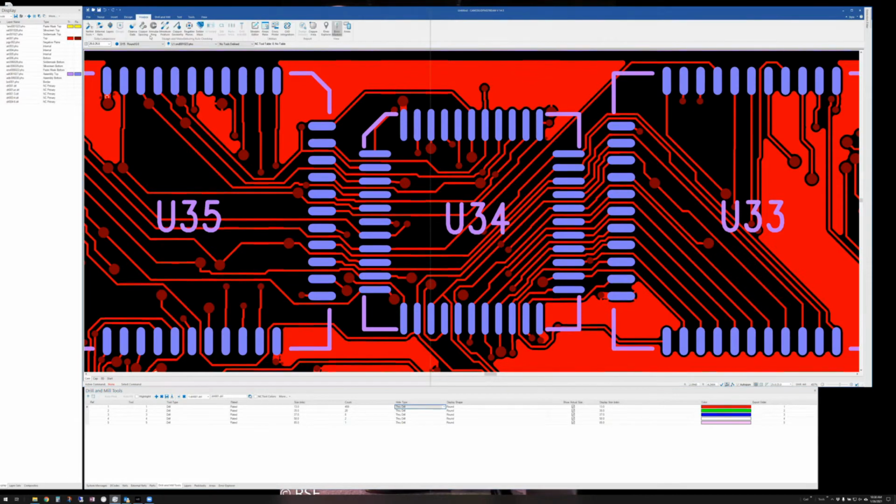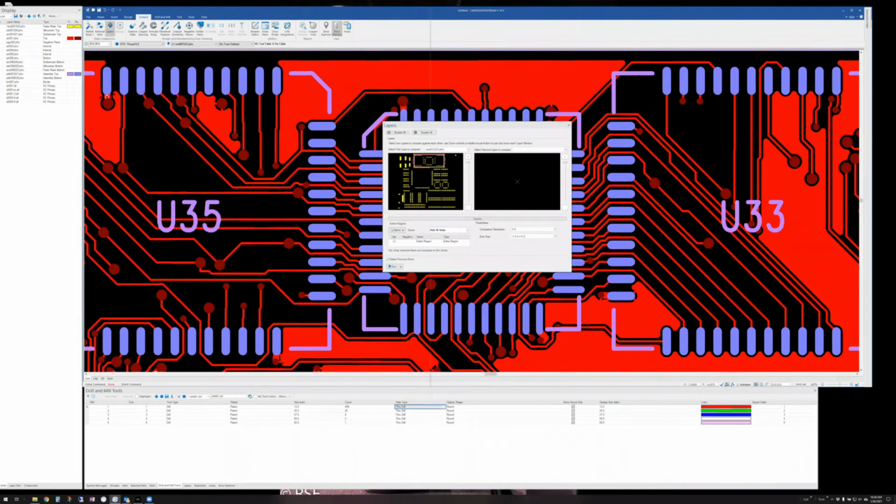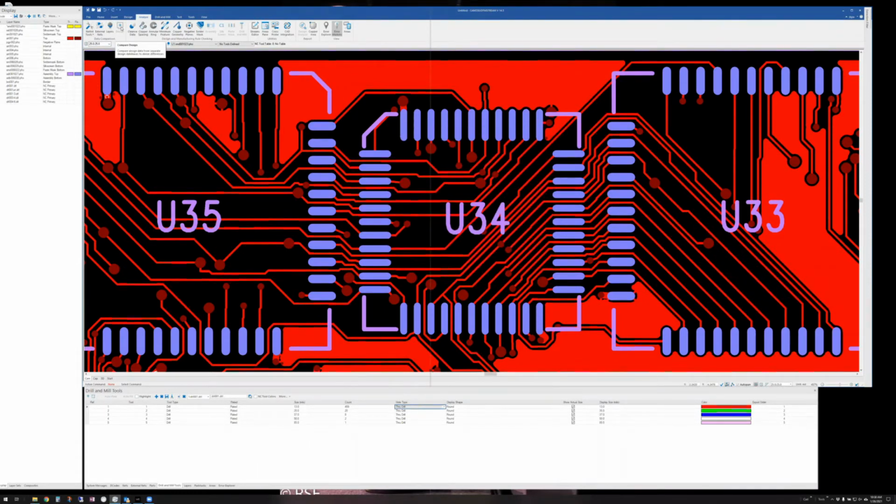So let me go quickly to Analyze, and we've already looked at these couple of options here. One of the things you can do under Analyze is layer compare in the 160. You just basically pick 2 layers that you want to compare and run it. If it's a different revision, you could just import that Gerber and then go ahead and run it. In the higher end DFM, there is a design compare, which will actually take 2 full designs and run the comparison. So it goes through each set of layers all the way through in one swoop, as opposed to having to go through each set individually.